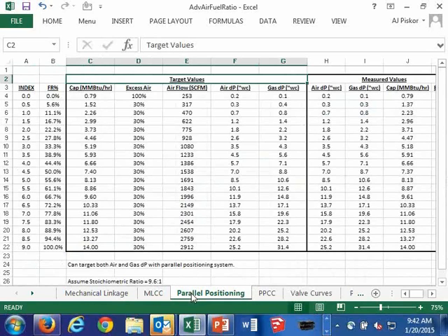So now that I have control of my airflow, I can now dictate what my capacity should be, not just at low fire and high fire, but all those other individual points. I couldn't do that before with the mechanical link system because my airflow is fixed. There's no adjustment, but now I've got adjustment, and what I can do now is I can specify, hey, as I have equal increments in firing rate or indexes, I can move up equally in capacity.